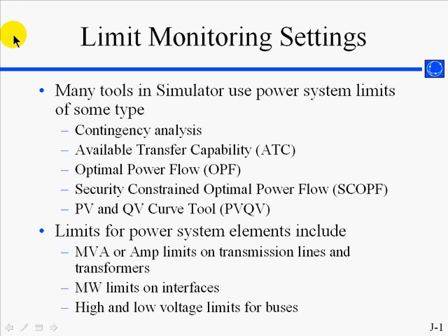In this session, we will discuss PowerWorld Simulator's limit monitoring settings. With limit monitoring settings, you can tell PowerWorld Simulator what is considered an overload or a voltage violation and what is considered a normal operating condition. Most advanced tools in PowerWorld Simulator use the limit monitoring settings.